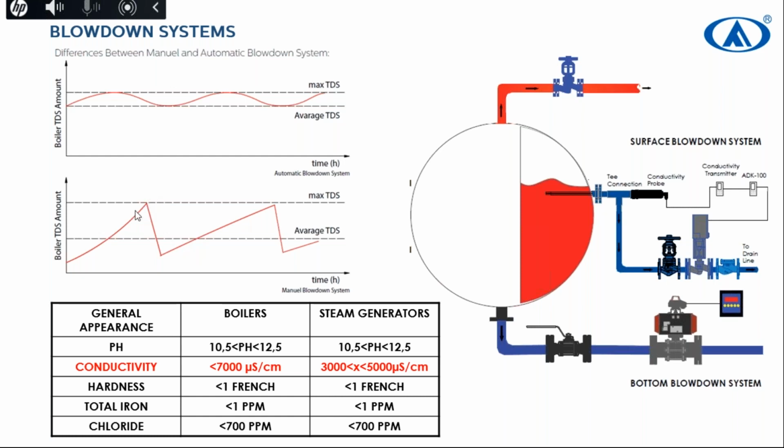But if you make less blowdown, you will send more dissolved solid water to your boiler, and it will cause some layers of sulfate, some layers of minerals, etc. And it will cause more bubbles, and these bubbles will make an insulation curtain, and it will cause heat not to pass to the steam, and it will cause a less efficient system in your line.